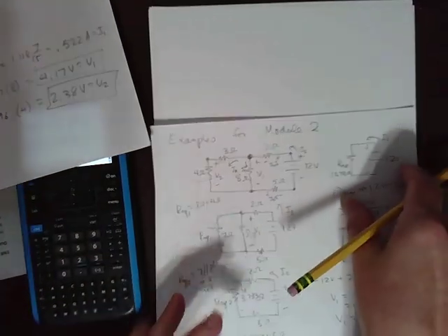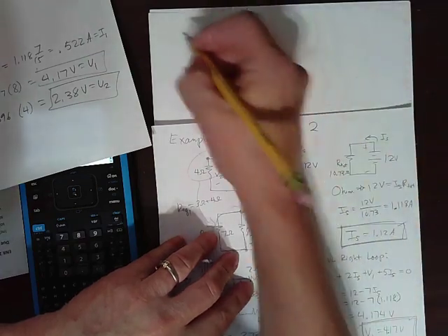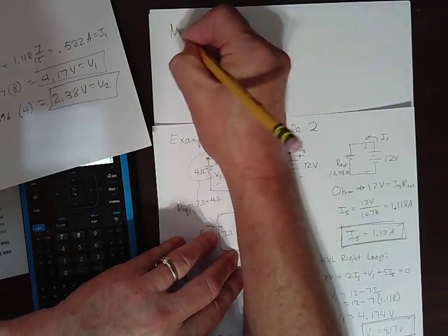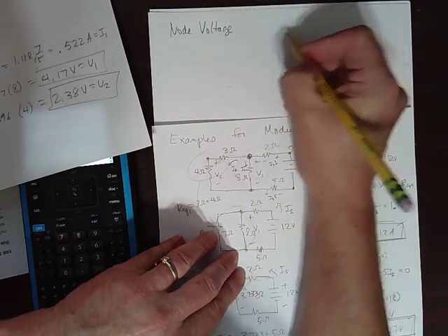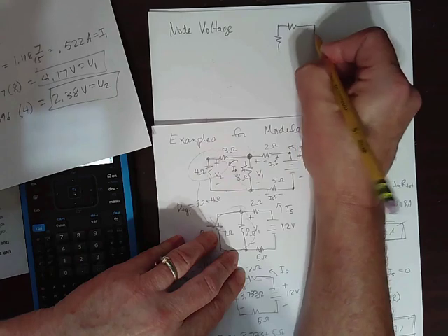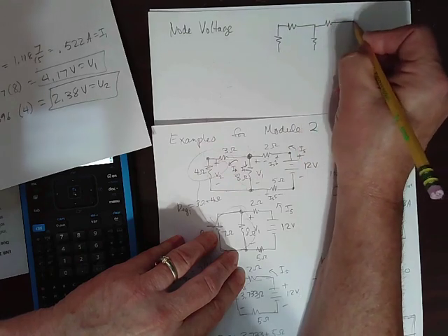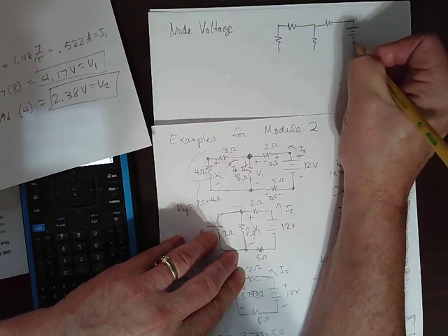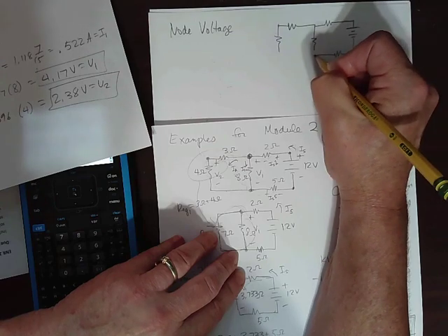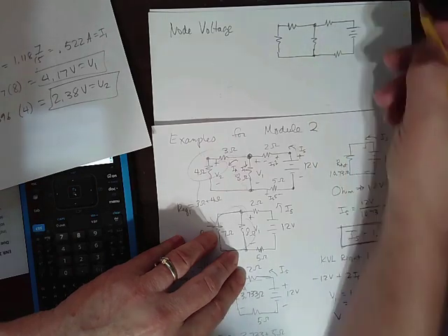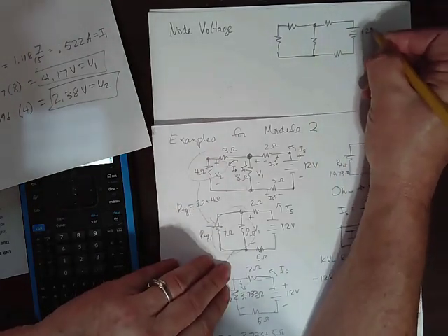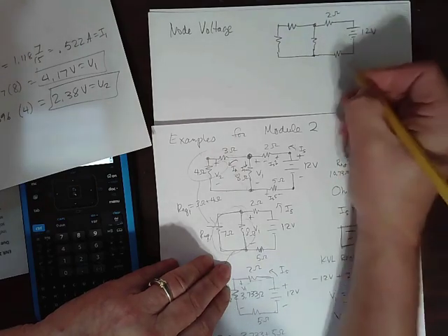Let's get our circuit back again. So let's do the node voltage method. So this is really a more standard actual method, and it's been standardized a lot so that it can be used with computer code and generates the equations in a nice standard form. So we need to learn it.